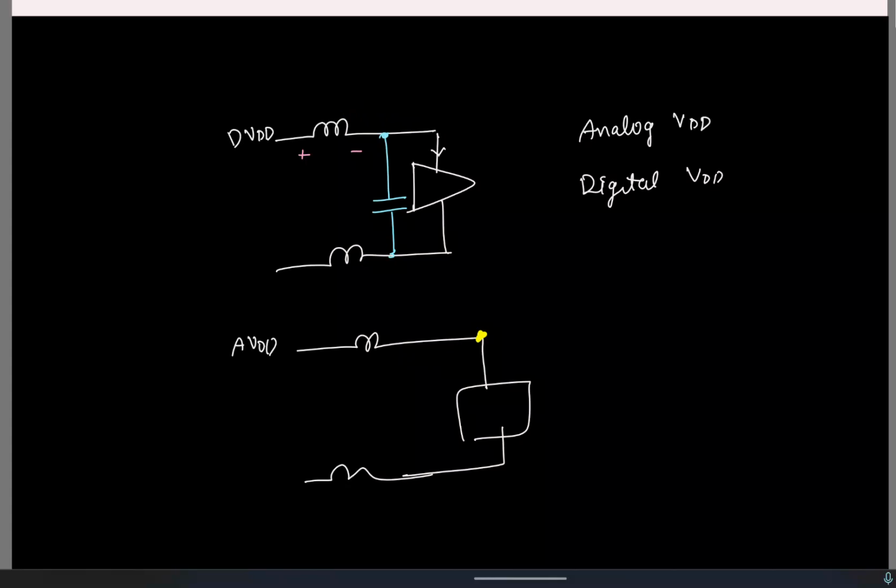And in general, if you want to have a very clean VDD, you try to have a separate pin for it. But normally we have only one VDD pin in a given. Depends. I mean, in your op-amps, yes. But if you take mixed signal circuits like ADCs or PLLs, you'll have circuits which are consuming static power as well as switching power. So for the blocks consuming static power, if you want them to be really good, you have to isolate them. Yeah, because in op-amps and basic circuits, you are dealing with analog circuits, right? So there it's okay. But the moment you have mixed signal circuits, where you also have some switching currents, then you'll have to do this isolation also.